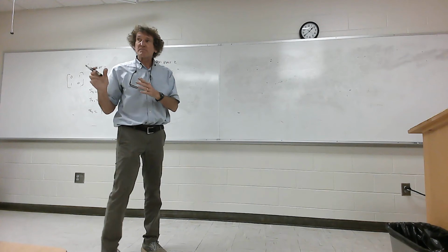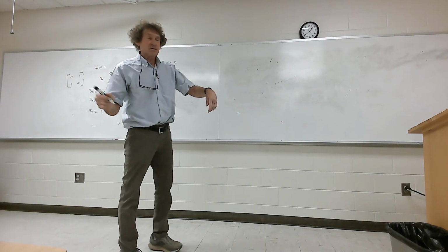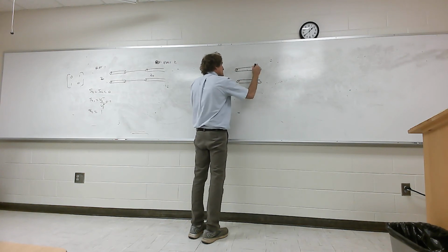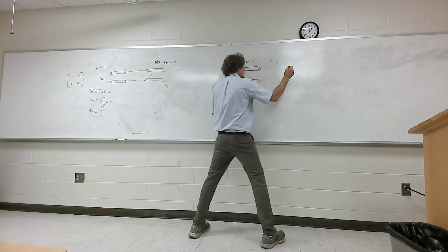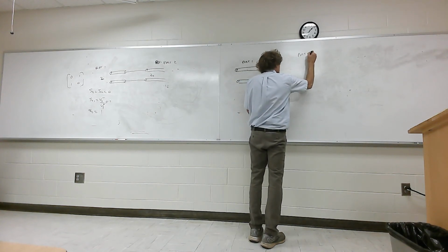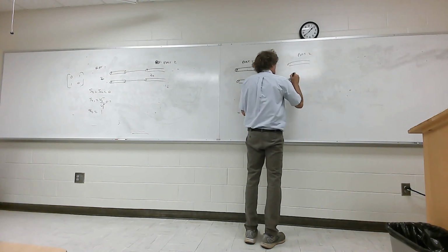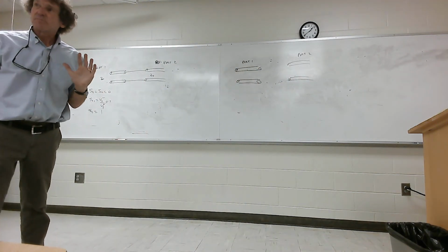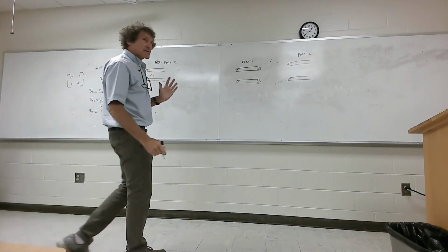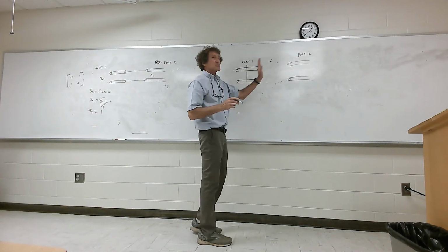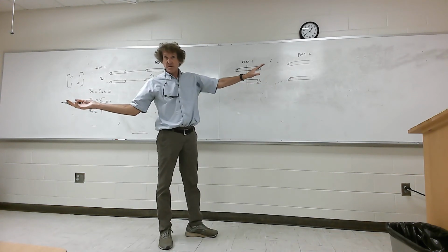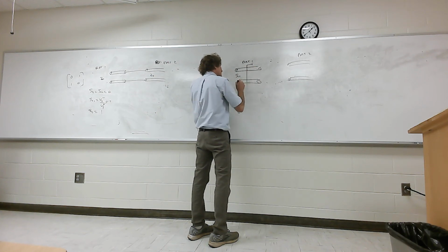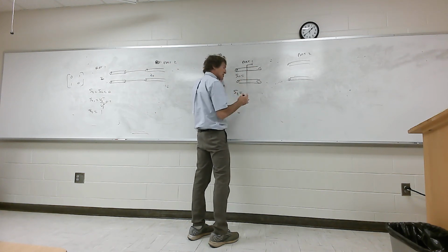Keep the thought. Remember, I'm just trying to make sure you get thinking the right way about this thing. What if you have this? Here's port 1 and port 2. No connection at all. Just look now. Think. When I look at this, first, is it a symmetric network or reciprocal? Yes. Isn't it just by inspection? Looks the same thing. So what is the reflection coefficient here? What is S11? Take a look.